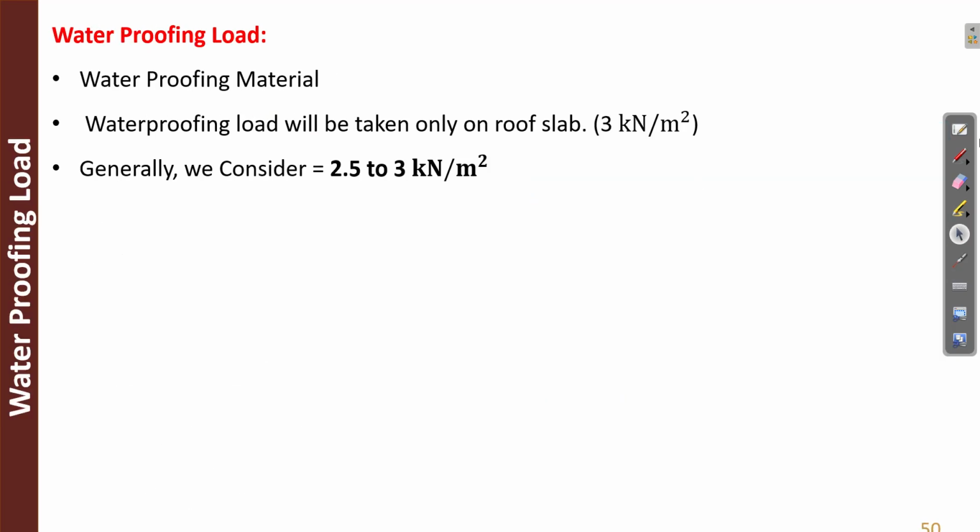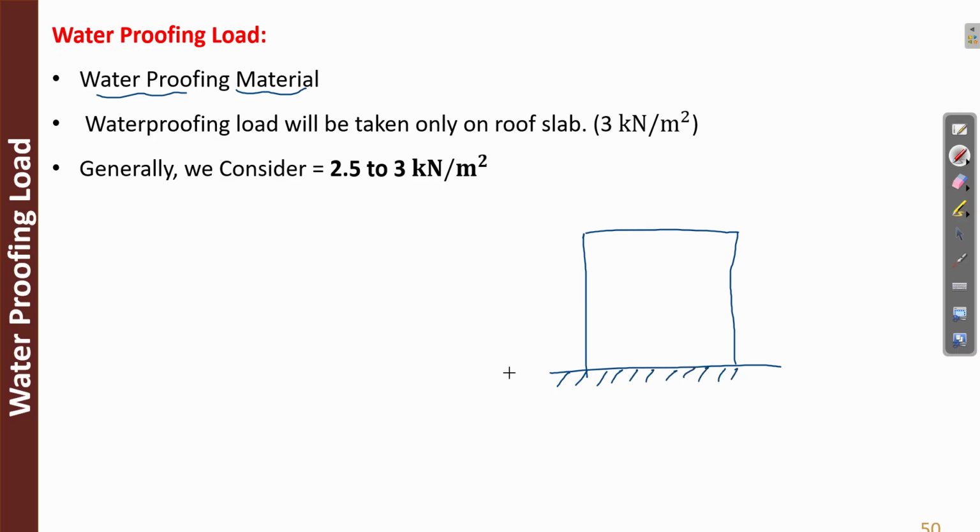So next is waterproofing load. It depends on the waterproofing material. Waterproofing load will be taken only on the roof slab. If this is your building, this is your base, and you have floors like this. So this is your last roof, which is exposed to weather actions.